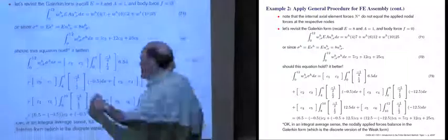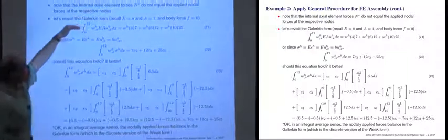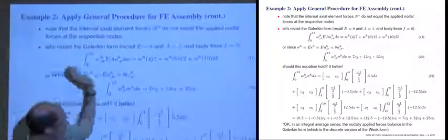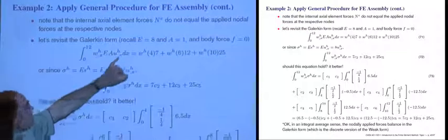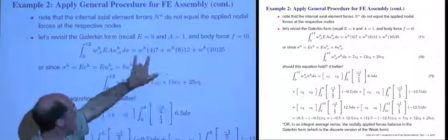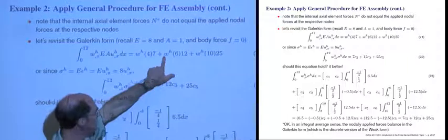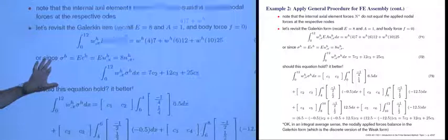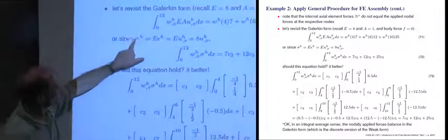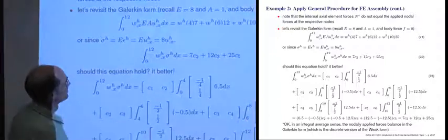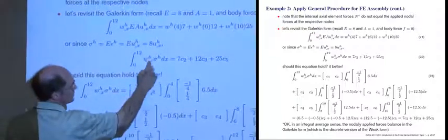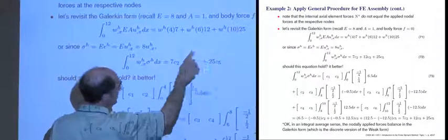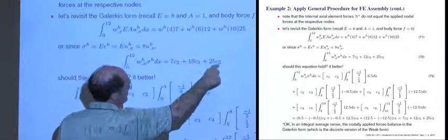So you can check this page more yourself. You can check the math. But remember, this is the equation we solved. Okay? So we solved this integral from 0 to 12. If you want to now think about it over the whole length of the bar, these are the derivatives. On the right-hand side, we had the weighting function evaluated at 4 times 7 plus the weighting function evaluated at 6 times 12. It's like that. Okay? So now if you consider that we know the values of stress, the stress is EA du/dx, and we can substitute into here. Now we have the derivative of the weighting function, and we have the C values. And the C values are also on the right-hand side. This is C2, this is C3, this is C5.